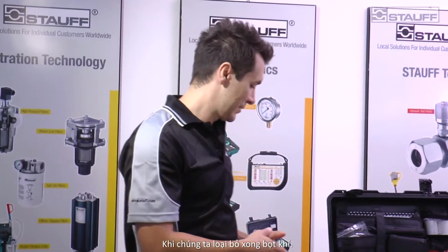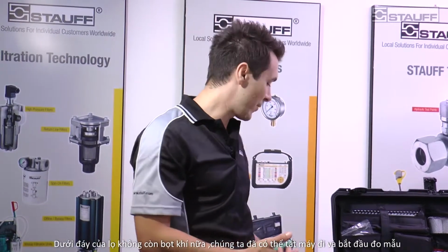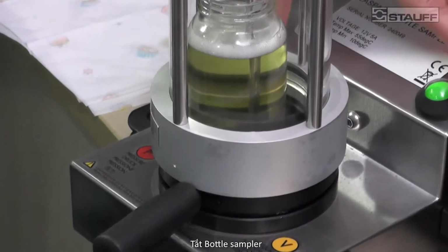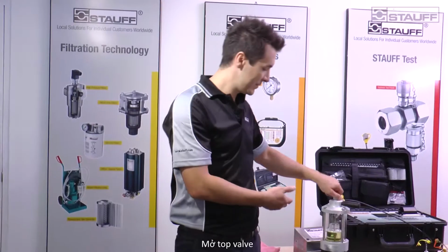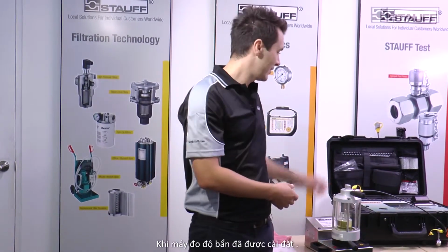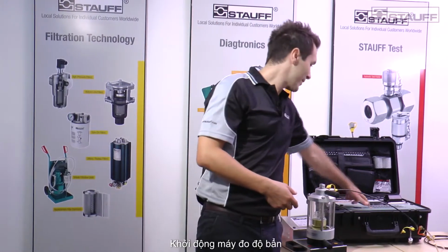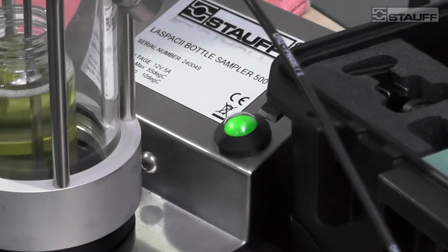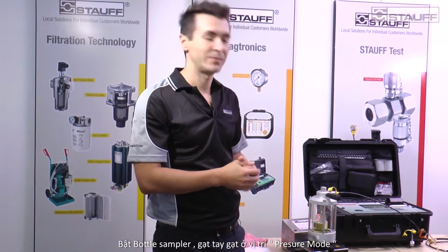Once we finish removing all the air bubbles, so there's no more bubbles down the bottom, now we are ready to turn it off and then commence the test. So we turn the bottle sampler off, open up the top valve, change the handle to pressure mode. When the machine's already set, make sure the machine's turned on, and then start the bottle sampler in the pressure mode.